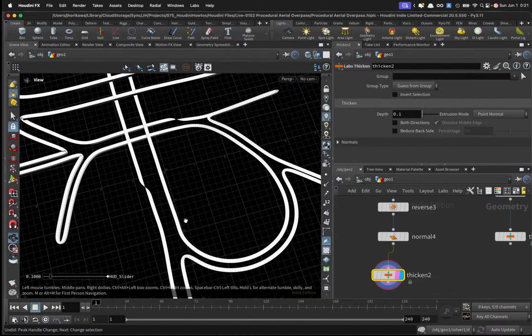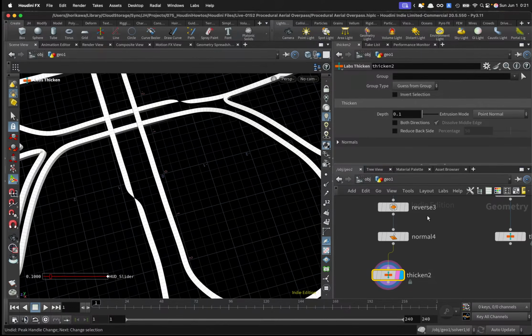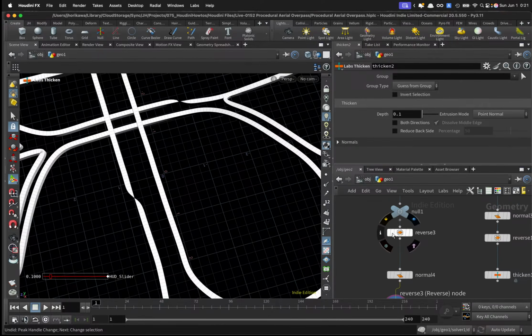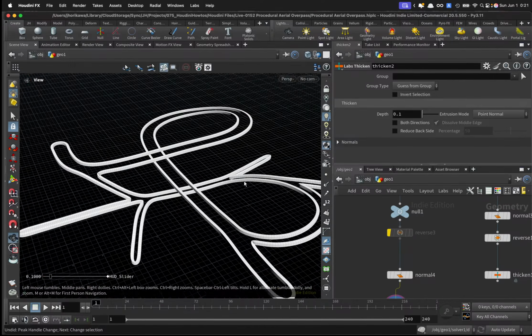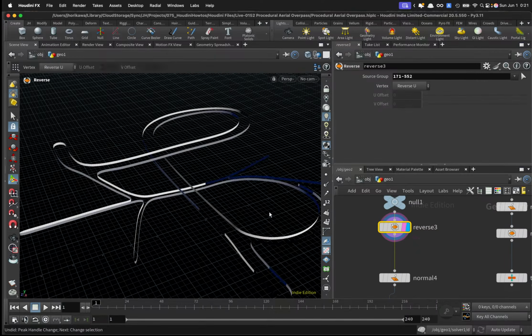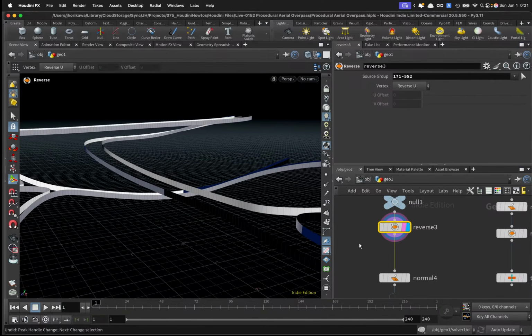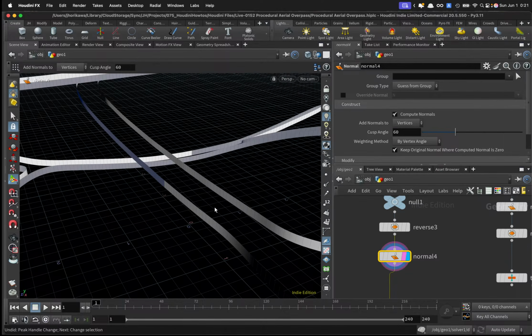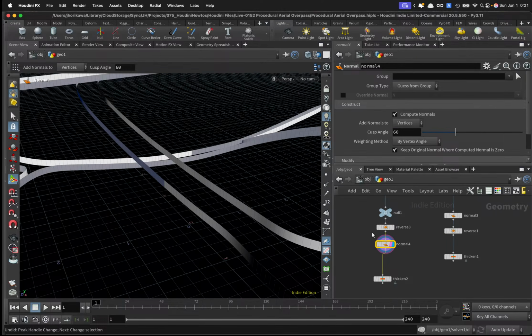Okay, so that's what I want to fix generally, procedurally. I actually didn't have that problem, but in the sample that I made previously, I had this problem. So what I want to do is start from this setup, having some errors on the normal directions for each face, and fix those face directions to have a consistent wall thickness all over the places.